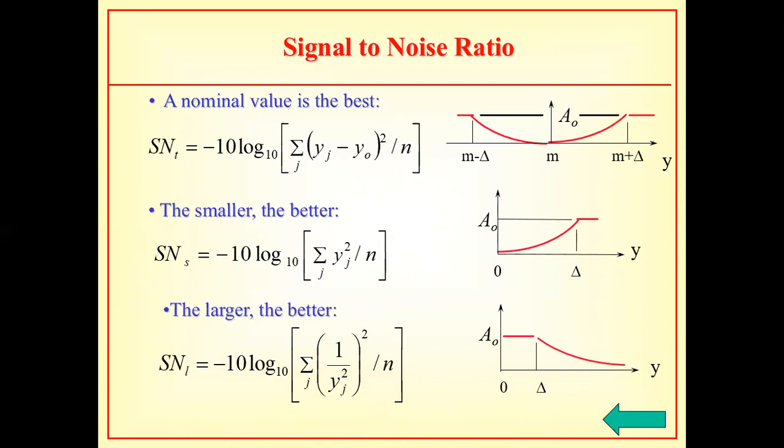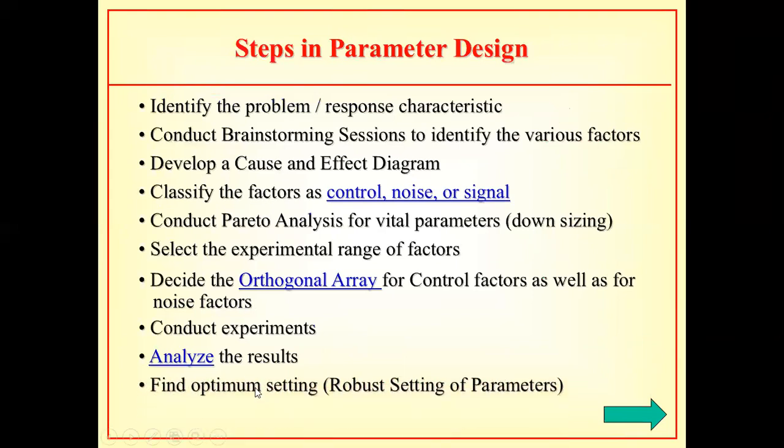Once you have this, these are the theoretical data. Normally in Taguchi methodology, we say S/N data. One was the raw data, on which we did the analysis. Now theoretically we are calculating S/N data. If I had done 8 experiments, I will get 8 theoretical data values, and I will do the analysis of variance on that also. That's how we optimize it. Once you analyze the result, you find the optimal setting and then confirm the results. Confirmation means conducting a repetition or more experiments to validate your results. These are the steps that we employ in Taguchi. That is all about Taguchi's methodology.